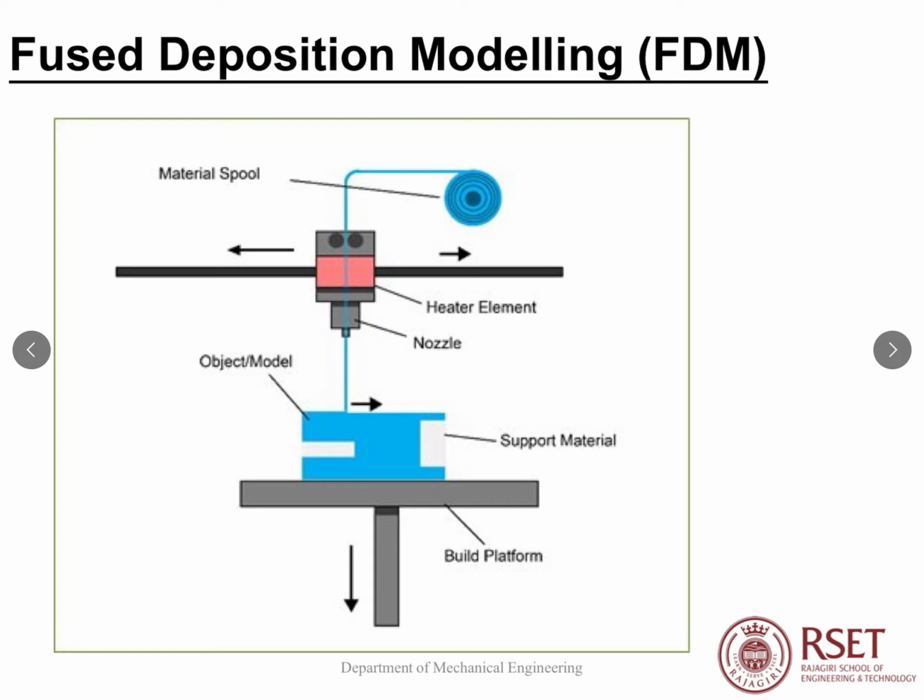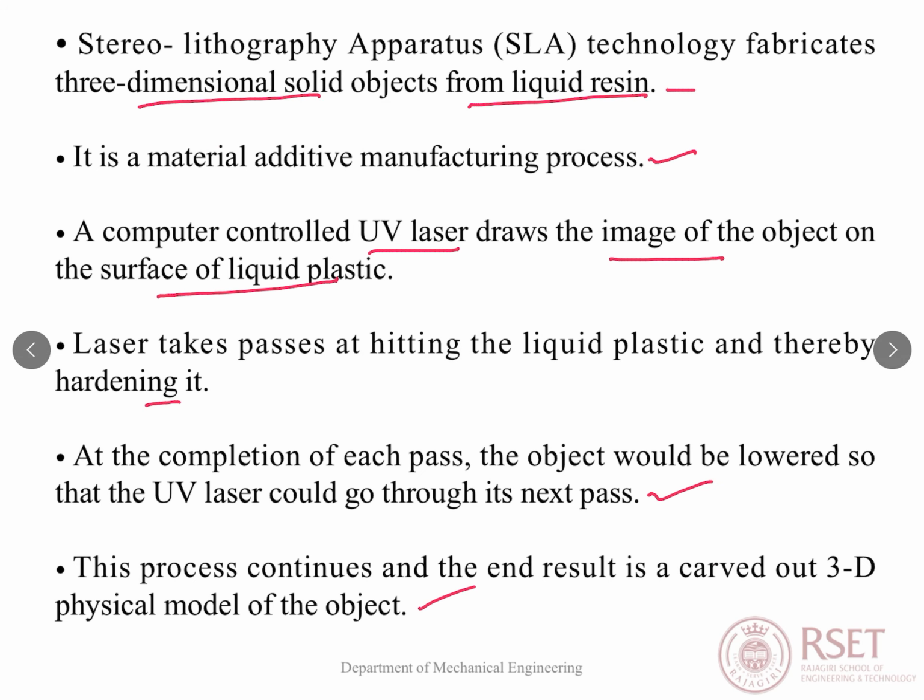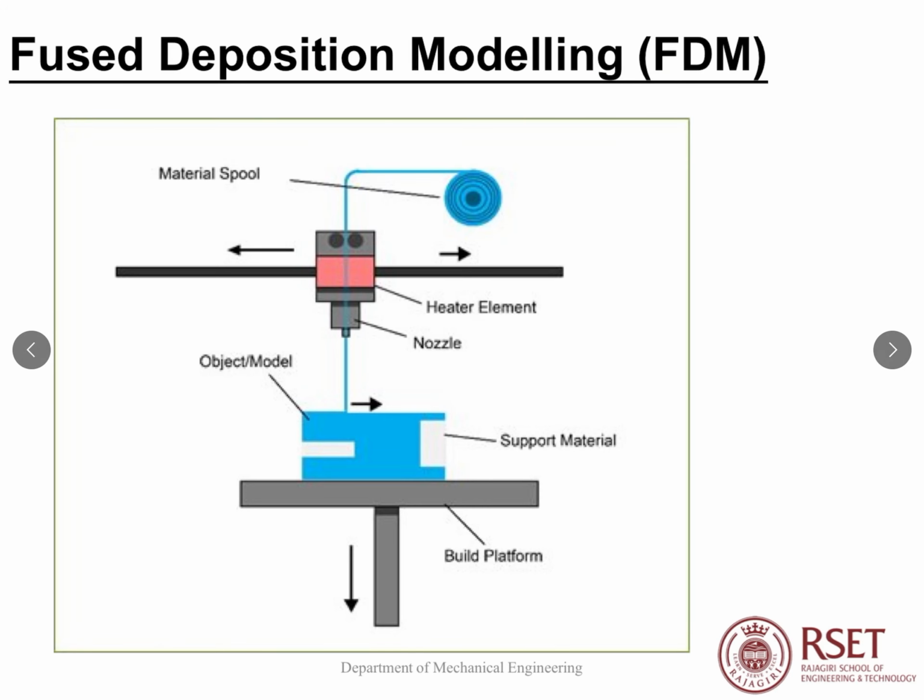That is about the stereolithographic apparatus SLA technique. Then we are moving to the next rapid prototyping technique, that is fused deposition modeling, FDM. It is also an additive manufacturing method by material extrusion. Here it happens as material extrusion instead of polymerization.